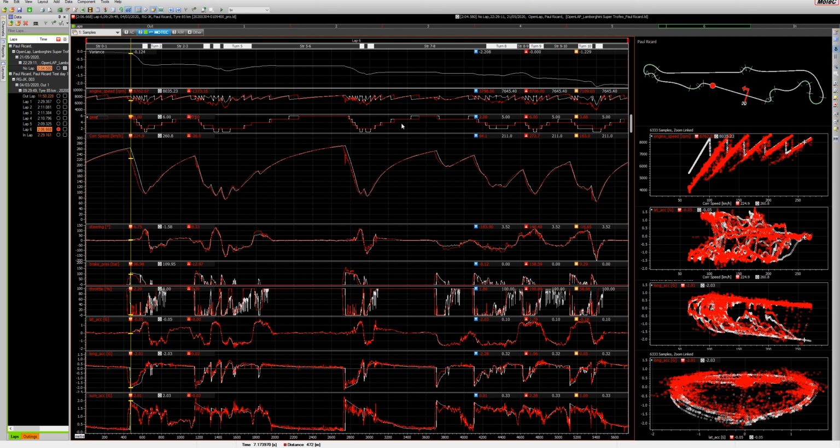In terms of gear selection, you will mainly see that the simulator actually uses mostly the same gears as the driver in reality, with the main differences being here in this region and here, where the simulator goes one gear lower. Although this might make sense in terms of torque delivery, we need to take into account the drivability of the car, meaning that sometimes it makes sense to stay one gear higher as the car is not that nervous.